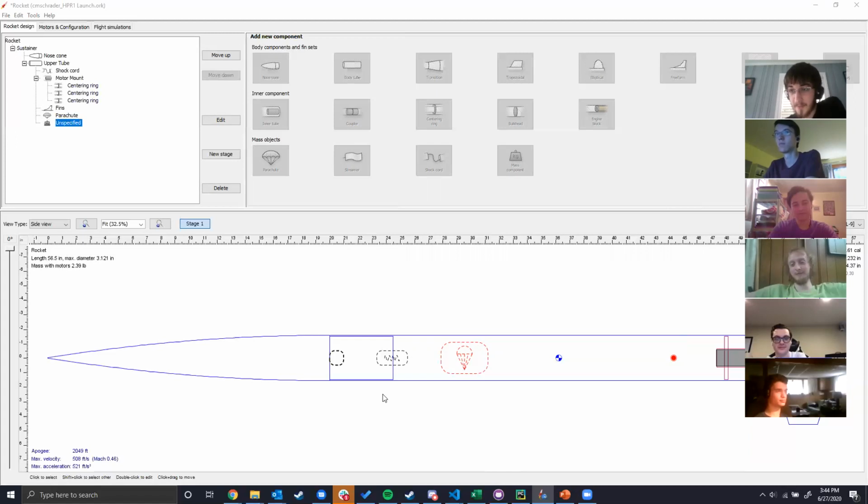Okay. And finally, another thing that's not modeled on here is the actual shear pins themselves. Shear pins are typically nylon bolts that go into the shoulder in between airframe sections, basically places where you want the rocket to separate. You can see here the shoulder on the nose cone. You'd have maybe 2 or 3 shear pins holding it on, and that way, once the ejection charge goes off, the force is such that the pins shear and the nose cone is able to break free.